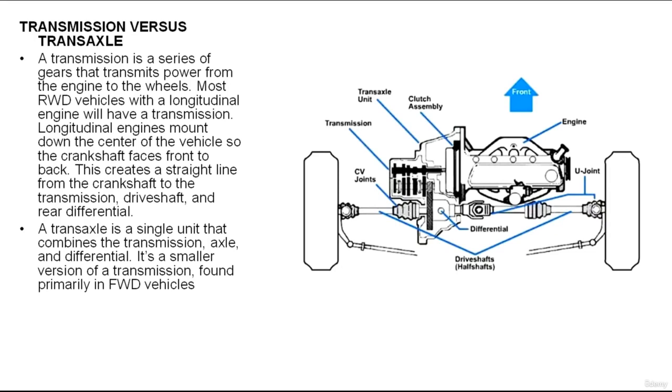One major advantage is the good traction on slippery roads due to the weight of the drivetrain components being directly over the driving axles of the vehicle. It's also more compact and lighter than the transmission of a rear-wheel drive vehicle. Transverse engine and transaxle configurations also allow for lower hood lines, thereby improving the vehicle's aerodynamics.